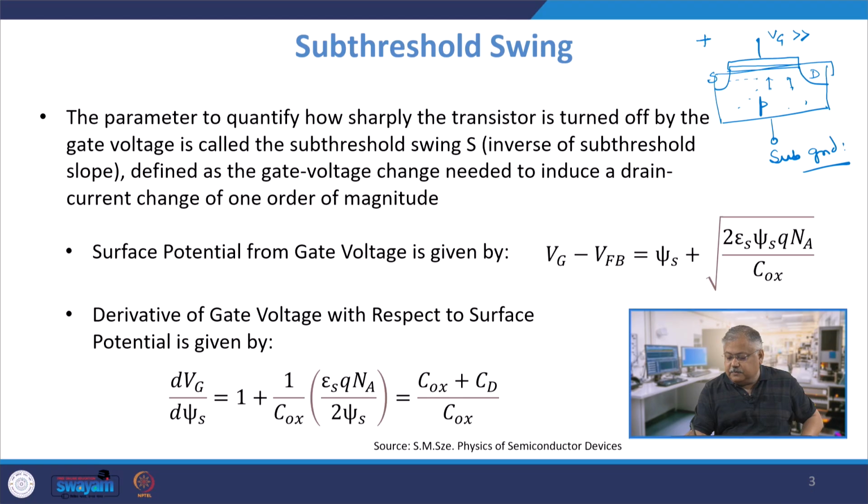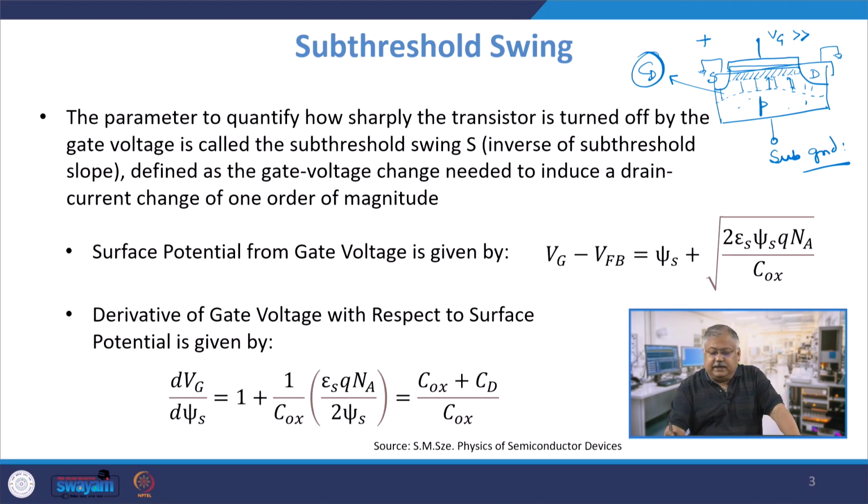Let us suppose there is an equivalent electron here if I do not apply a bias. This is grounded, this is grounded, and let us assume that there is a bunch of electrons coming here. Therefore, there will be a depletion region which is something like this, right. This will be the depletion region. Now, this depletion region's capacitance is referred to as Cd, and this is basically a bias dependent capacitance, because if you go on adding potential on the drain side, you will be reverse biasing this depletion region from the substrate to the drain, and therefore this will extend into the inversion region, right. That is what you are all aware of, that the inversion region will go down to a very low value, right.